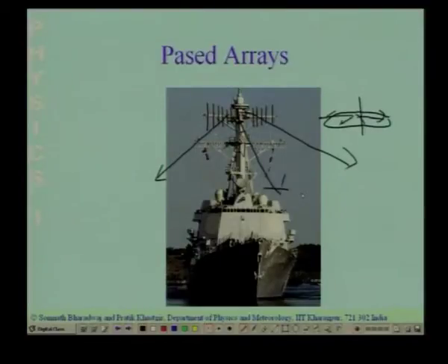This can be used as a radar. You can send out the signal and receive the signal that gets reflected back from any distant object. You can make the radar sweep around the whole plane by providing an appropriate phase difference between the dipoles and then slowly changing the phase difference.